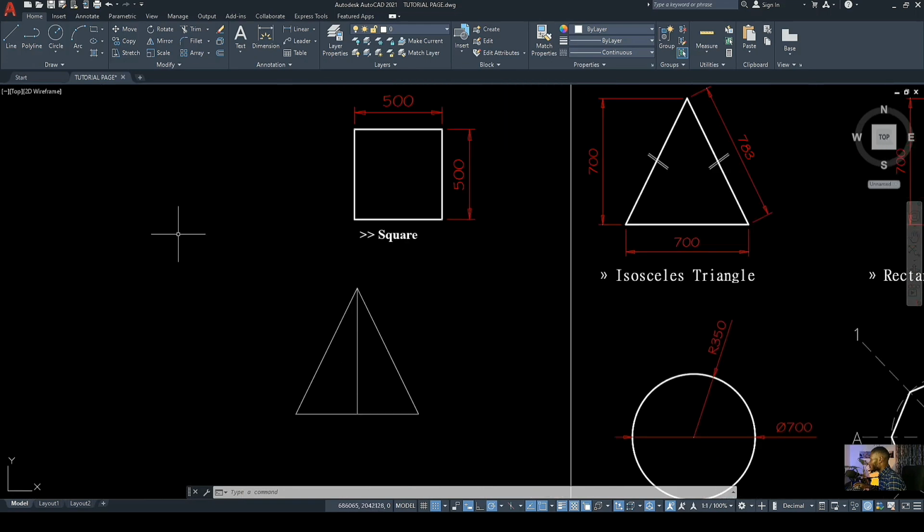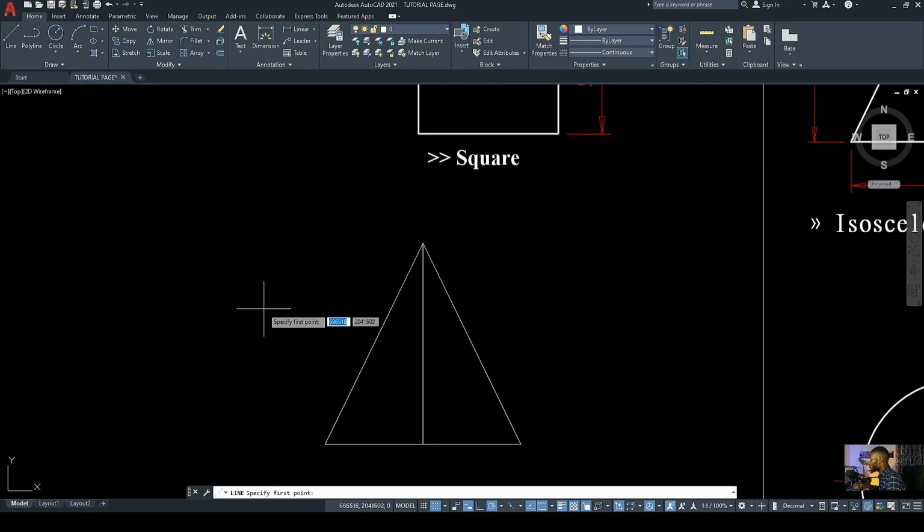So to get such a line, we can now pick our line. You see, since our restrict cursor is on specified angle, it will enable us to do something like this. You can pick a point, then you navigate till you get a 45-degree. Let's see how to get a 45-degree. Once it's snapped at 45-degree, you click and leave your line. You see 45-degree, we have it already.